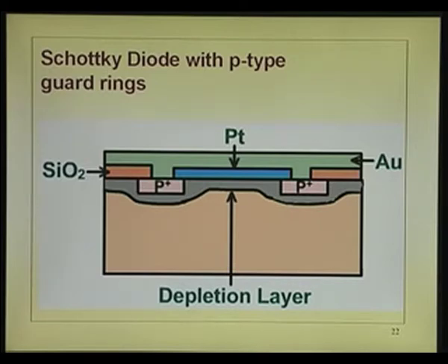So, this is the P type guard ring or P plus guard ring. You can see the plot here shows the metal here, and this is the oxide, okay, and this is the metal put over the top of that. The Schottky is only here. Okay. This is actually a Schottky, and the junction is shorted out here through this gold. Okay. Now, how does it help? As far as this diode is concerned, I will just better draw that on the board to make it a bit clearer.